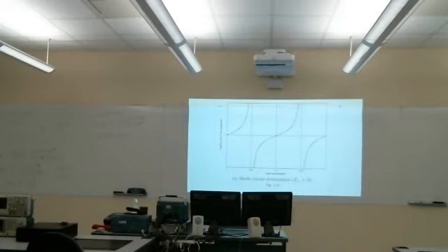What that often means that we have to do, given a particular load, is maybe put something in parallel with the load, or put something in series with a given load, so that we change the load impedance so it's equal to Z0. So it's called impedance matching. So the question is how to do that.